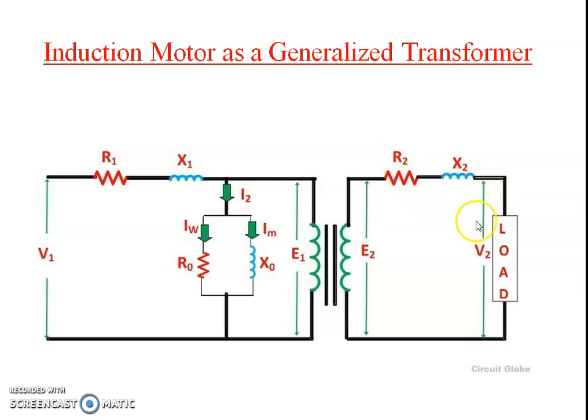So how much will I get here? I will get 219 volts in V2. Where did 1 volt go? It dropped here because of resistance. If the secondary winding has no resistance, then whatever the E2, that is 220 volts, I get here; that is, E2 is equal to V2. When? When there is no resistance here, or the resistance is very low.